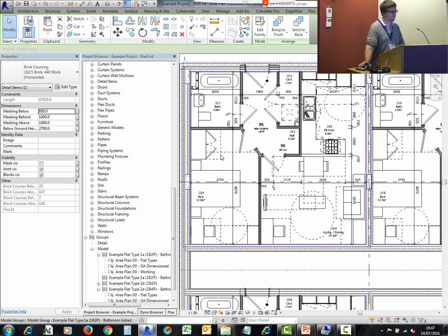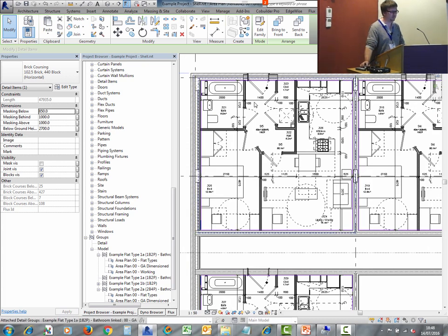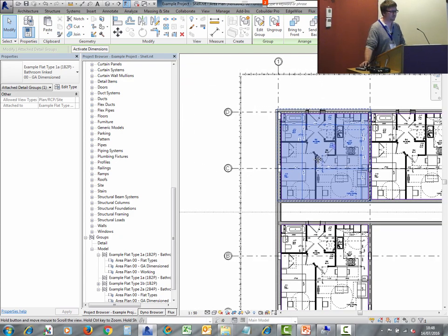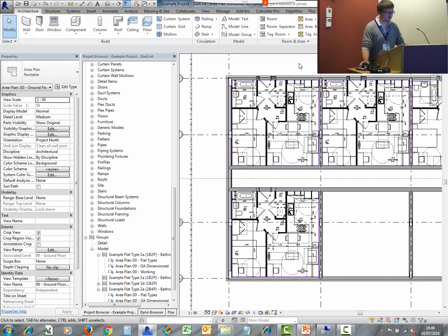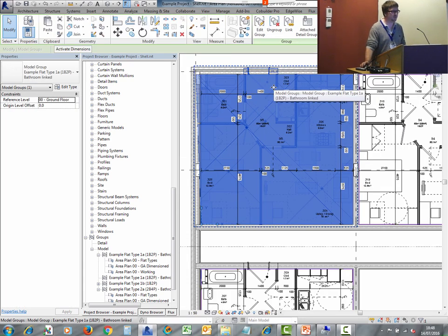With the annotation, tagging, dimensioning, that top instance of the group, this one, to be on the opposite side. So first you've got to see annotation, and so globally, or is it? Yes. So you can do something similar with linked files. Sometimes the annotations flip. Yes, that's true. I've had that problem before, and sometimes what I do is create a duplicate of the view in the model group, and I reorientate the dimensions in the way that will make it read right. But that is one issue.